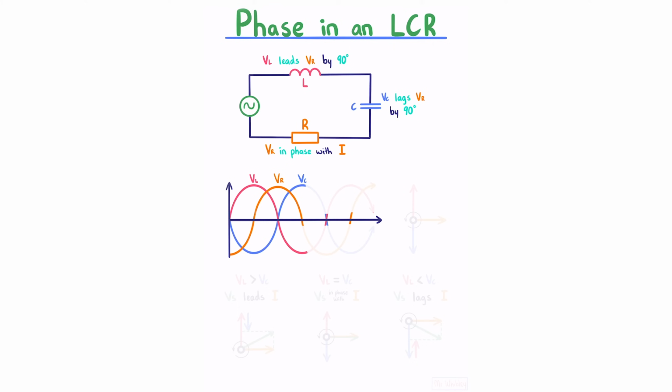Our capacitor once again discharges, increasing our current, which reaches a point of zero rate of change, resulting in once again zero voltage across our inductor, and so on. Representing that on a counterclockwise rotating phasor, we see our inductor voltage and capacitor voltage with a phase difference of 180 degrees, and our resistor in between, where, as stated above, our VL is leading our VR, and our VC is lagging our VR, keeping in mind that this is rotating in this direction.